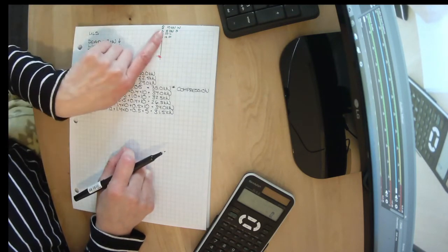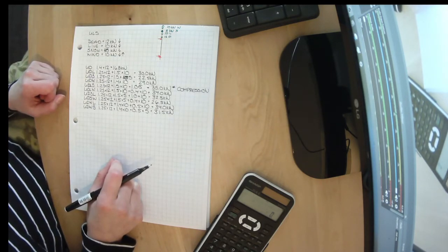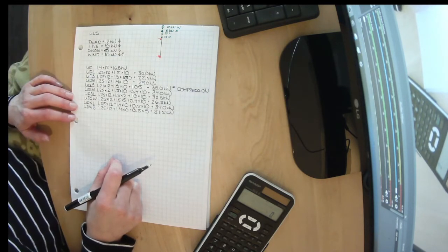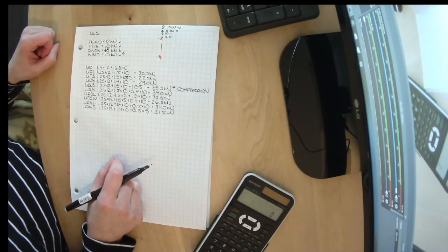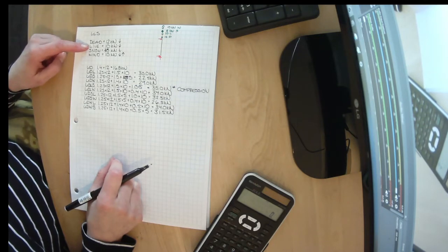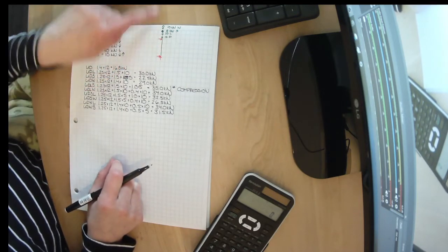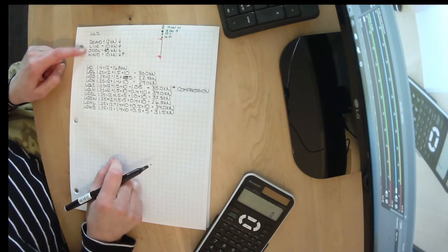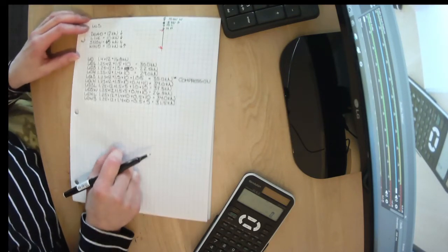But if wind was acting upwards, we'd want to make sure that we didn't guess there was too much dead load on it. So we'd probably want to use the 0.9 load factor for dead, and we certainly wouldn't want to assume that there was live or snow there. Remember, if we're worried that this could pull up out of the ground or stretch too much, we wouldn't want to make the assumption that live or snow were there, because those would be helping us out.